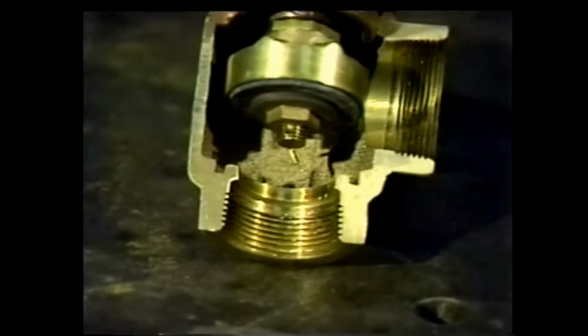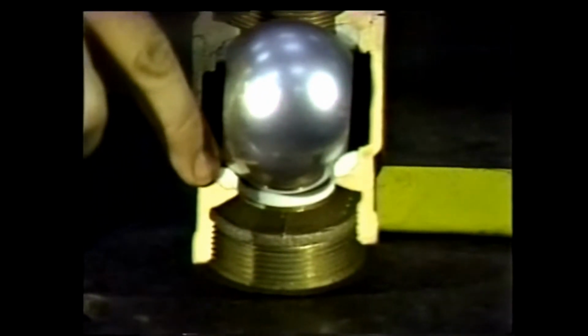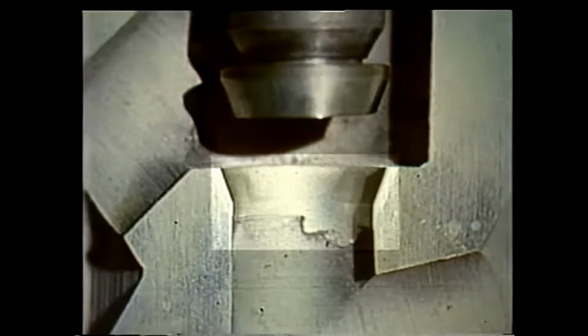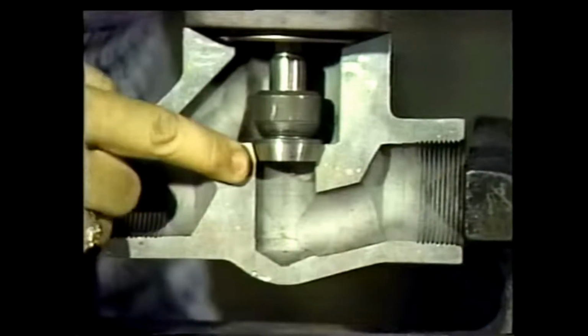The materials used in constructing a seat will vary depending on where the valve will be installed. For low pressure, low temperature systems such as service water, the valve seat may be made of bronze or a Teflon type material. In systems requiring high temperatures and pressures, the seating area must be very strong. Stellite, a commercial name for an extremely hard metal, is often used. This metal has proven to be highly resistant to damage due to leakage of steam. The disc is part of the valve that presses against the seat to stop flow.